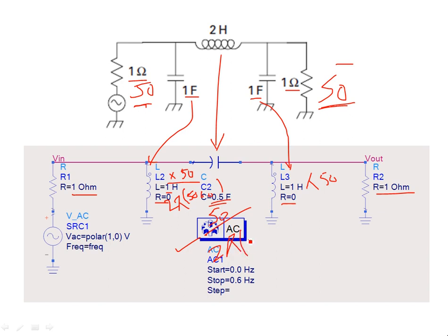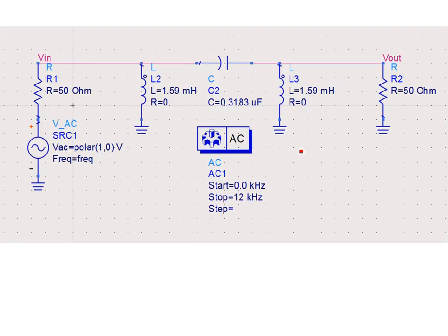So this is the third order Butterworth high pass filter, and if you do the same over here as well, you have to divide this by the same factor. This is the circuit you're going to get. Okay, this is a third order Butterworth low pass filter. Oh, sorry, the high pass filter, third order HPF, and this is denormalized. Okay, and this operation is happening at 50 ohms.